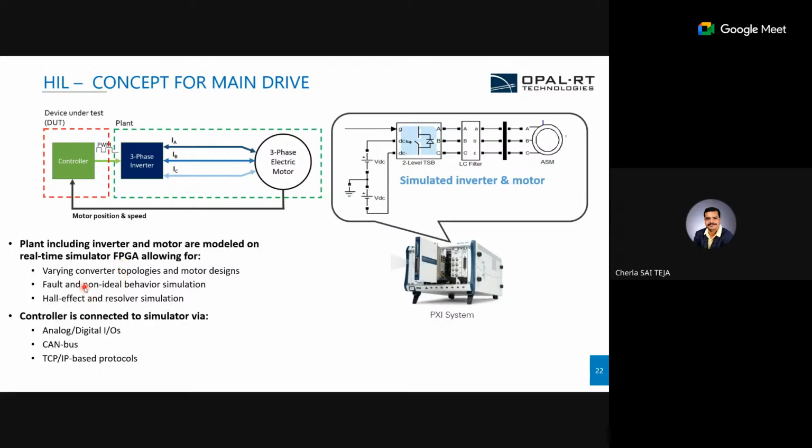So with one FPGA today, as I told, I can go for testing a PMSM drive, tomorrow an induction motor or SRM motor. So we can have various converter topologies and motor designs. We can go for fault and non-ideal behavior simulation.